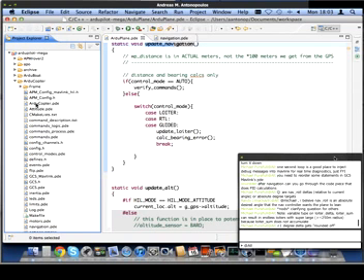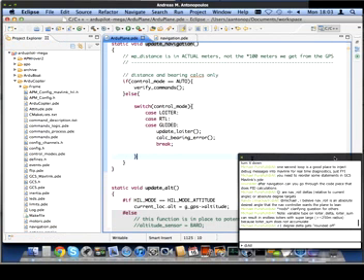So it tries to track your altitude based on what it calls the altitude error. The altitude error is just the difference in centimeters between the altitude that you're trying to achieve and the altitude you're currently at, and it tries to get that altitude error down as small as possible.